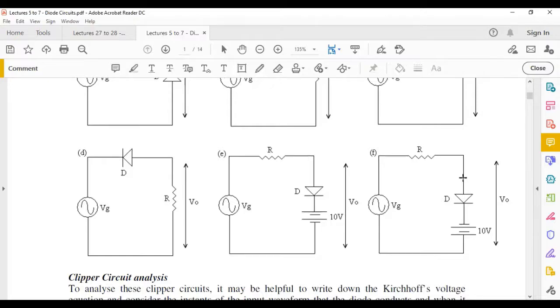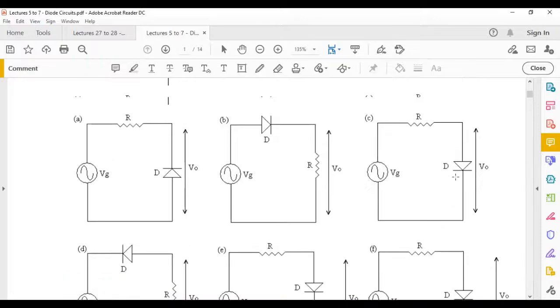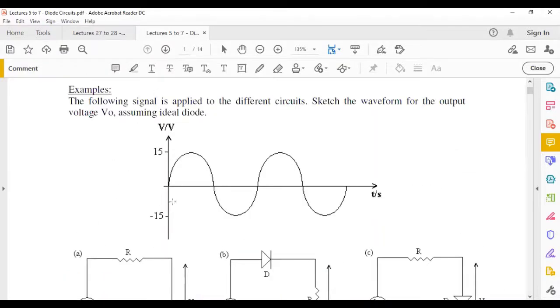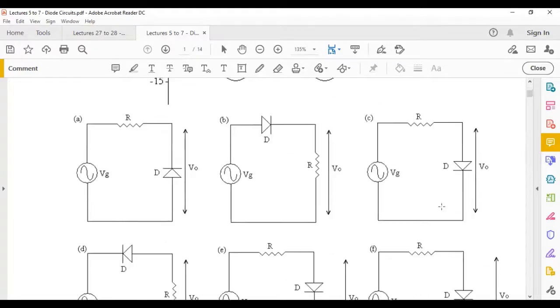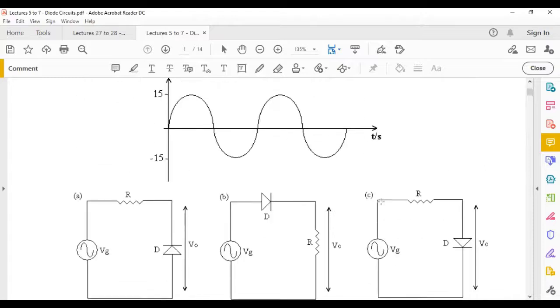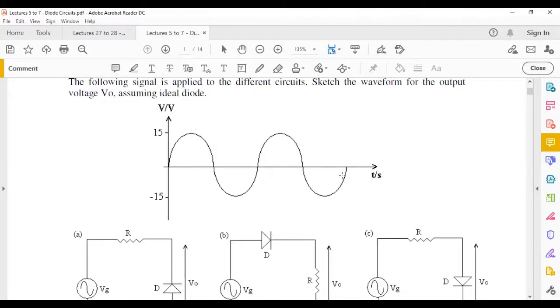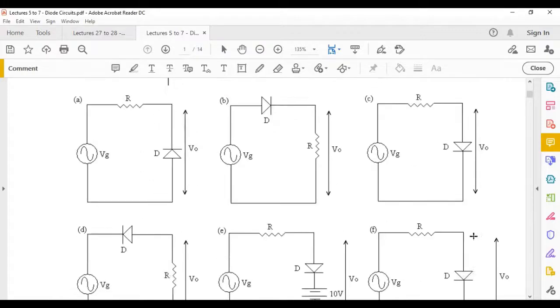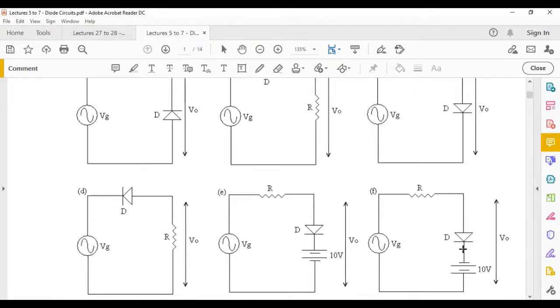So if it is minus 9 volts, minus 8 volts, and so on, it means on your waveform you would have a minus 10 volts threshold there. As long as it's above that, your diode is forward biased. If it is forward biased, you're measuring minus 10, so it's going to cut at minus 10. And then when it's below minus 10, imagine this is minus 10 and this is at minus 11, this is going to try to conduct in the reverse direction. So this diode will be open circuited. This is an open circuit.